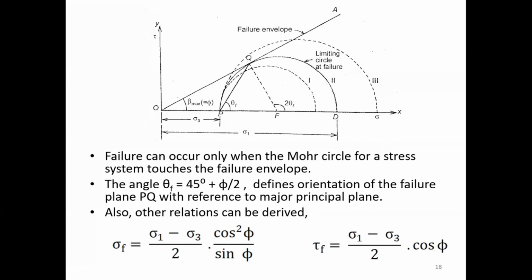So for any system of stresses, you can develop these, and you can identify whether your soil is going to fail or not, and you can also identify all the different planes on which different system of stresses act within the soil using this. I hope the Mohr circle and its construction and its application is clear.